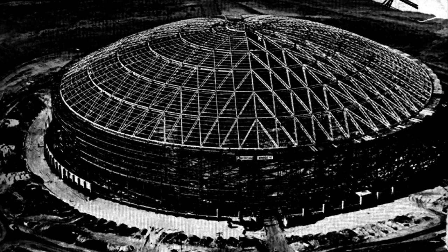We've got a series of radiating arms coming in one direction. We've got the circular sections, which, as you now know, are in tension because they're gripping, if you like, the dome together. And then we've got diagonals working together. So all of them working together develop these very large spans.